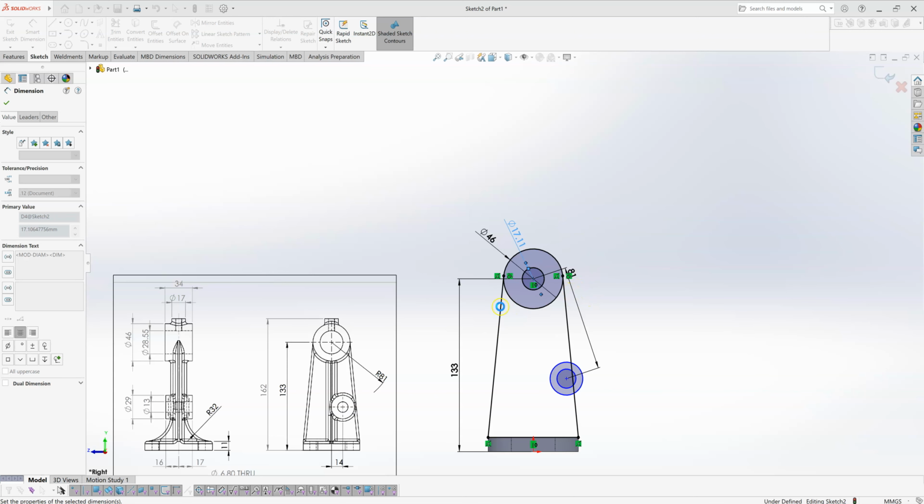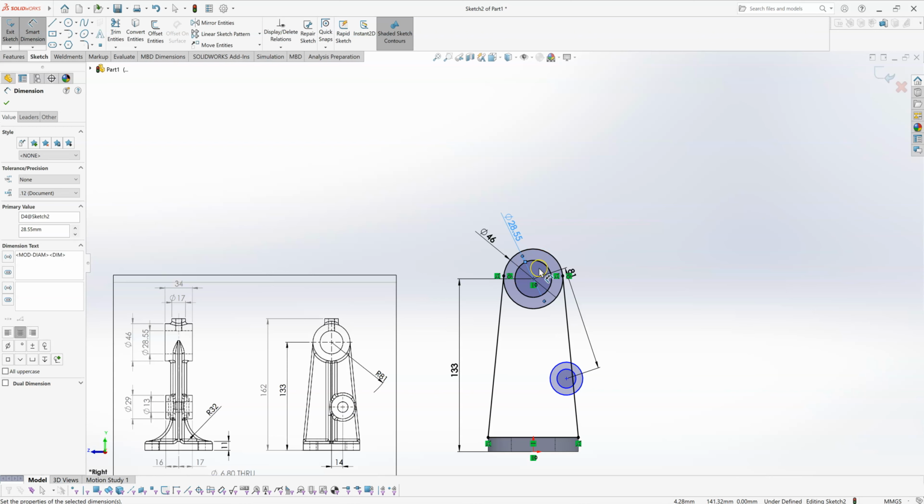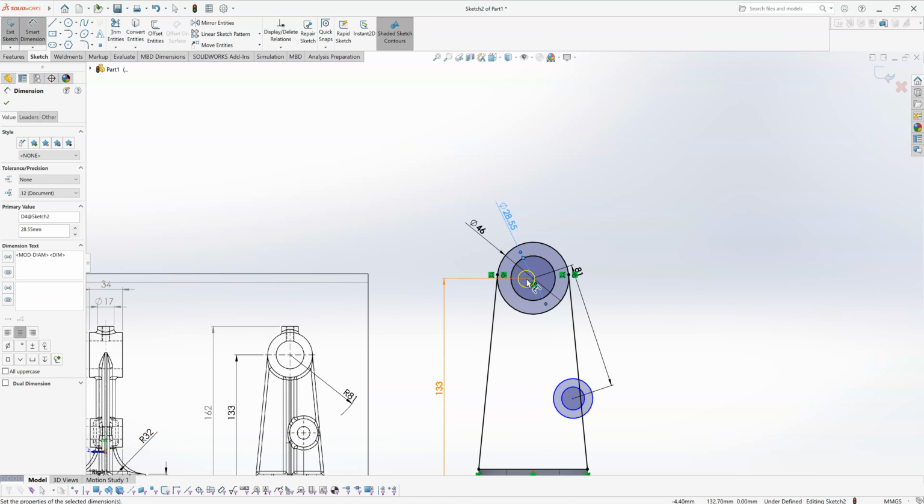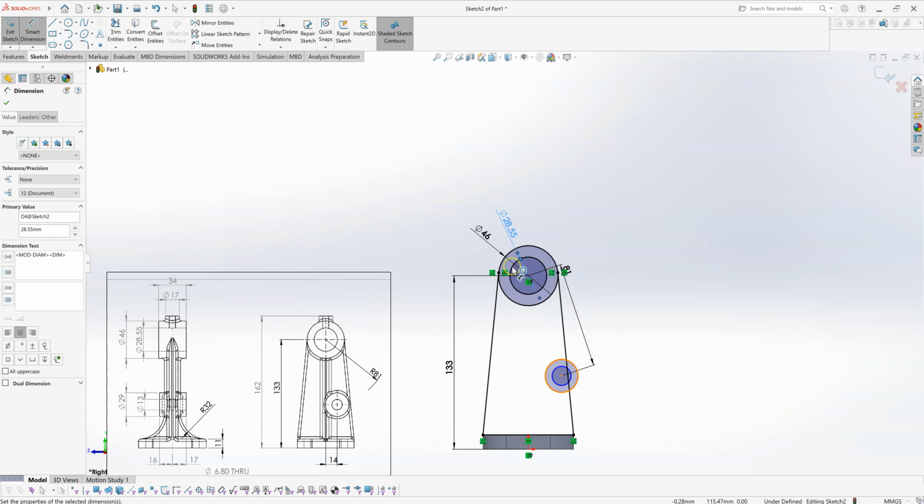Okay. Now you could just extrude this as a solid cylinder and then cut that hole as a separate feature. Maybe it might make sense. Maybe using the hole wizard if it was something other than just a plain hole. I'm going to just do it this way within the sketch. It's probably the quickest way to do it, but as I said, if this is any kind of a non-standard hole, you might use the hole wizard for it. Okay, so the shape of that is coming together now.